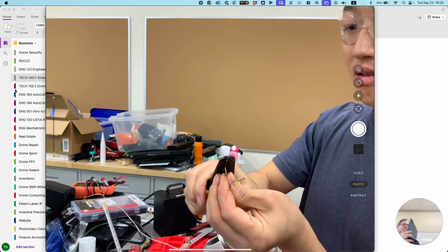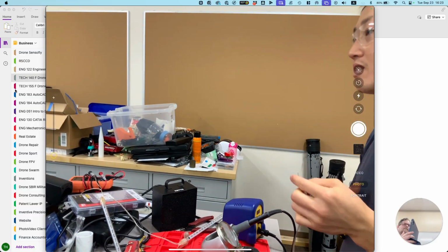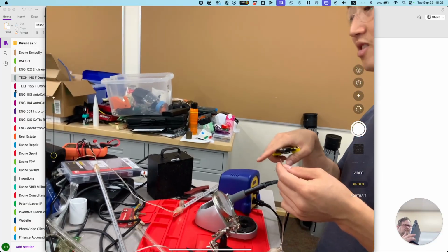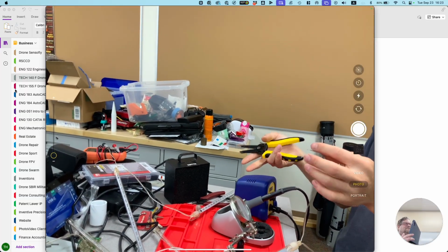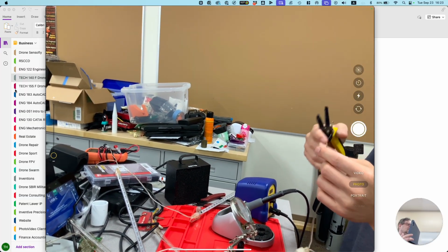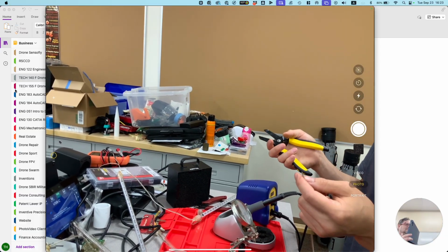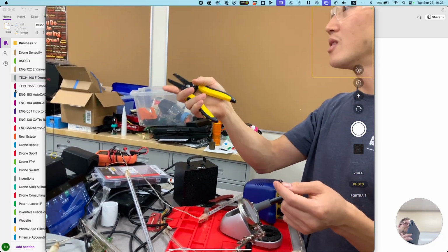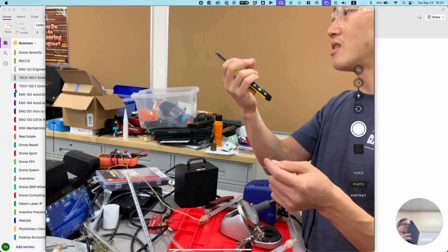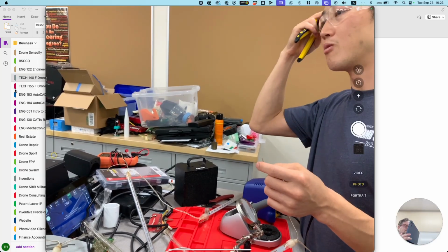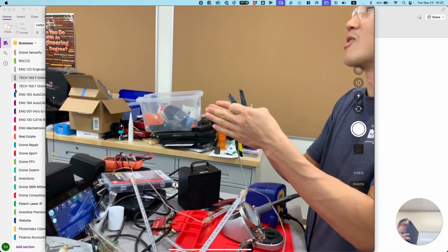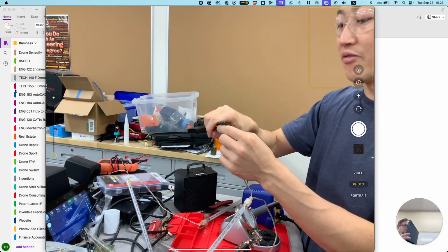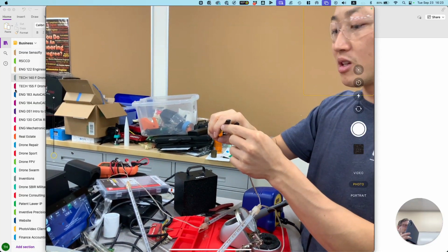In that case, if you went ahead with fewer strands, would that make it more prone to failing? It might. In this case, this is a low current application. LED lights don't use that much current, so the risk is like nothing's going to happen in reality. But if you did the same thing on your motors, it could heat up. It could localize heating at that point. Think back at your water analogy. Now you're using a thinner pipe, and you're forcing all this to go through. Yeah, exactly. So that's what can happen, and it can fail at that point. Failure is mostly through overheating.